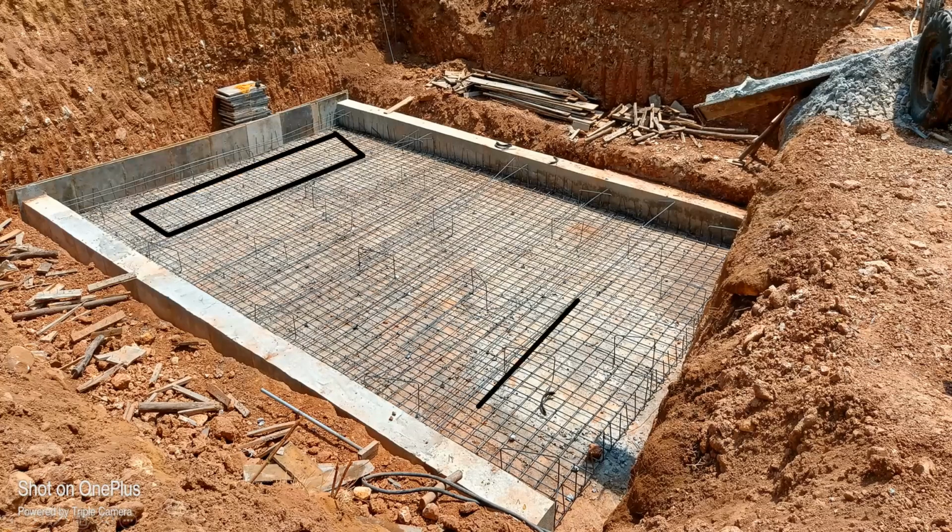In the drawing they might have written that your abutment should come here, and this will be the width of your abutment, and this is how your abutment should come. Okay, this is a marking what they have given. So what we do, we bring a bar, we cut a bar according to that, and then we keep the bar inside this. We'll give an L to that, otherwise it won't stand, isn't it? One L on this side, one L on the other side. So in this way we try to keep the reinforcement for the abutment.